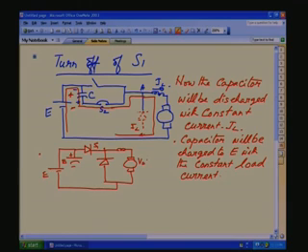From the buck converter we know V0 is equal to input E into T on divided by the total period T. So for a variable voltage, the output voltage depends on the T on. So our half resonant period TR should be much less than the minimum T on period. So one condition.